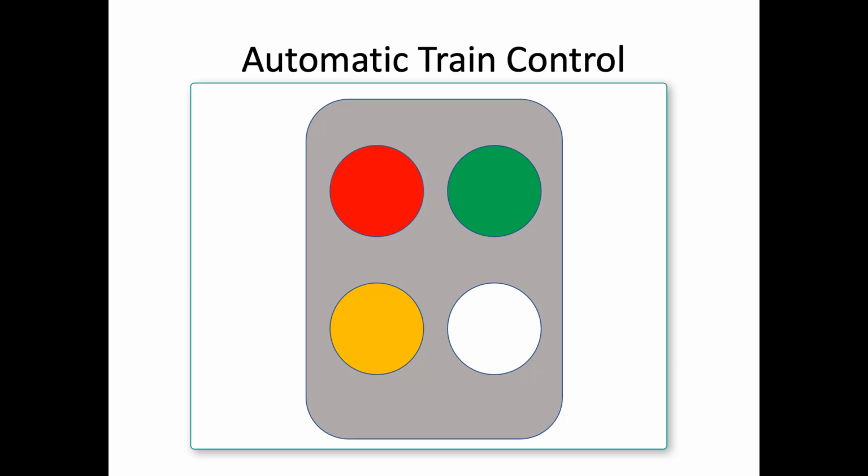Now, however, with the coming of positive train control, or PTC, UP has installed their four-indication cab signaling equipment, again with no wayside signals, along with CTC and the PTC system, thus making the automatic train control, or ATC, redundant, and as a result has discontinued the old ATC. And I'm sure no one misses it too much.